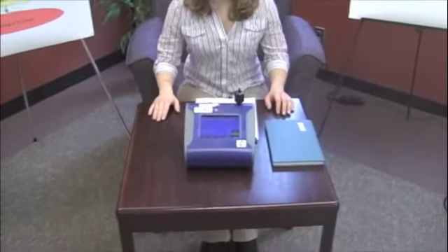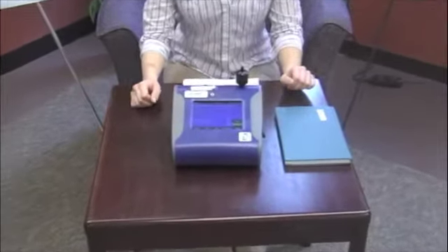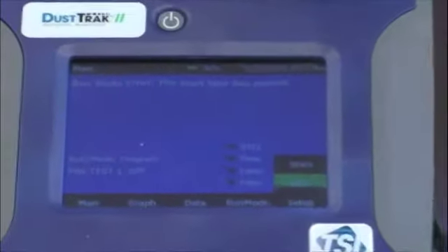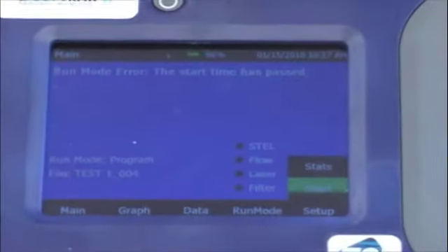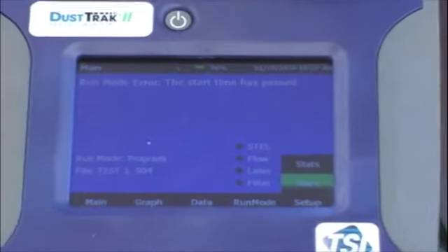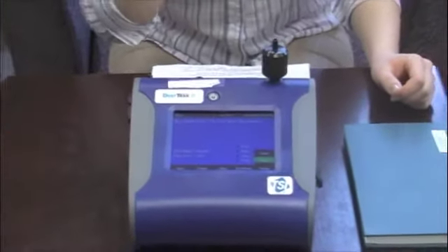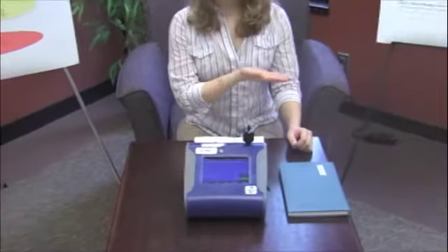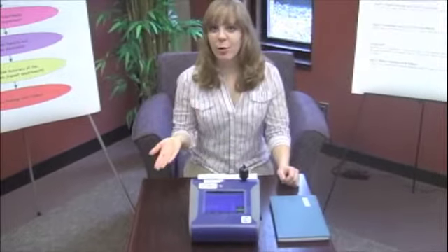Okay, now we're ready to test the hypothesis. The air quality data I gathered, and that I'll be sharing with you, was collected using the DustTrak aerosol monitor. The DustTrak is a real-time portable particulate matter concentration monitor, which measures particulate matter in micrograms per cubic meter. The DustTrak pulls in air through a small nozzle and then records the concentration of the particulates. The monitor has logging capabilities, and its calculations are reliable exposure assessment of the particulate matter concentrations corresponding to respirable sizes of 10, 2.5, and 1.0 microns, or PM10, PM2.5, and PM1.0.